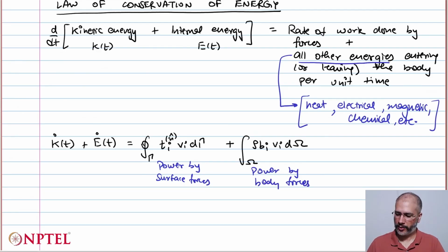For the present consideration, we will talk about heat, which can be written as a surface integral because the heat or the heat flux typically enters from the boundaries of the body, like you're heating a body over a flame or you contact a body with a hot or a cold body. So that is energy transfer from the bounding surface of the body. So this can be written as a closed surface integral over this bounding surface of some heat flux vector, which has units of watts per meter squared. So that is the rate of energy entering per unit area.